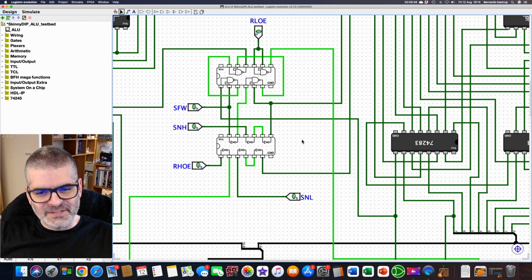My intuition and my experience tell me I don't need to go overboard with Schmitt triggers here. Here, I needed the inverters anyway, so I would either use a 7404 or a 7414. I needed the inverters for this signal. This signal absolutely needs to be inverted. This does too, but I could invert it in the other chip.